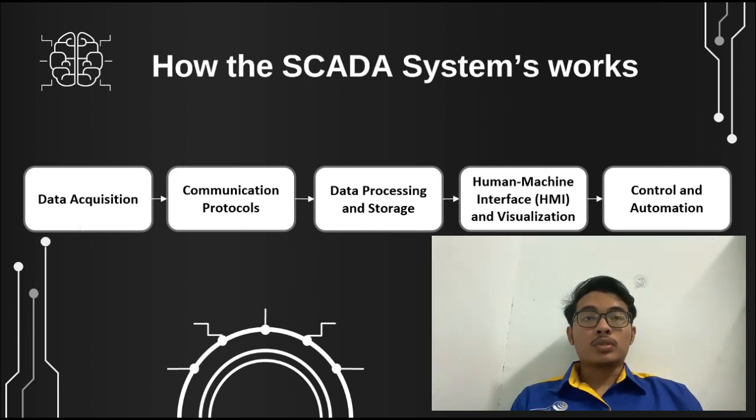Lastly, control and automation. Based on predefined logic, control algorithm, or operator input, the SCADA system allows operators to issue commands or set points to control devices. Control actions facilitate adjustment in process parameters, enabling optimization and maintaining efficiency in industrial operation.